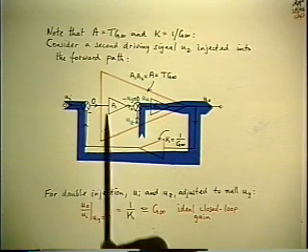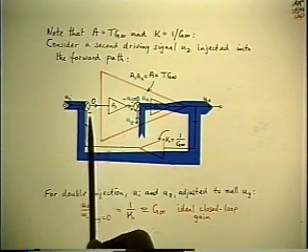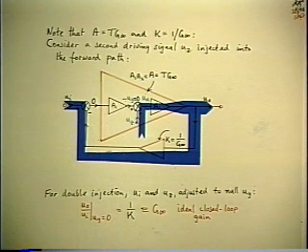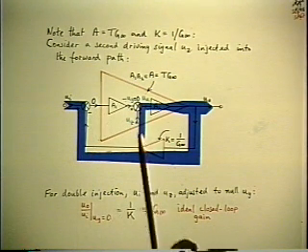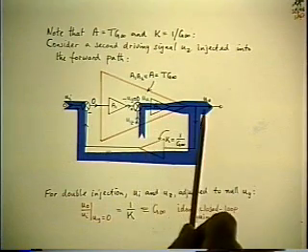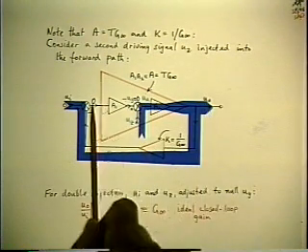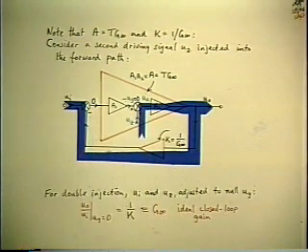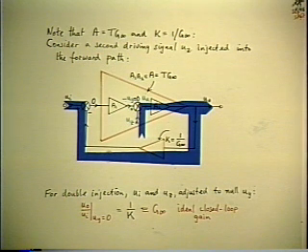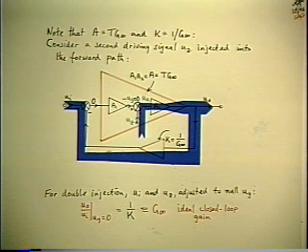So you don't need the error signal anymore. That's actually what you're doing when you set up the null condition. You're adjusting the second input in such a way that it drives the output to take over the role of the amplified error signal. So this is another application for null double injection, besides the extra element theorem.